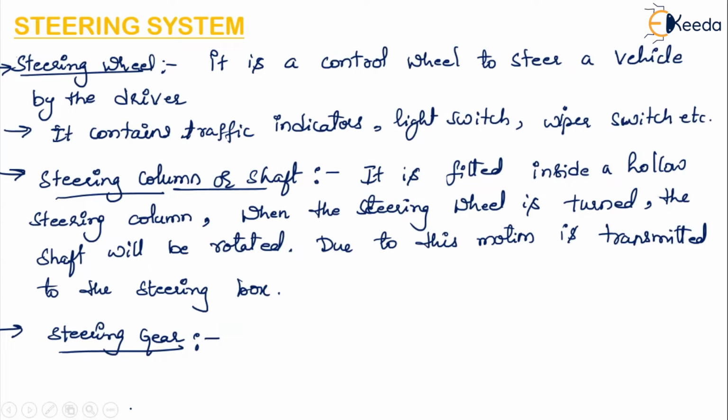The steering gearbox contains the gears that transmit the driver's steering input to the steering link that will turn the wheels, and it multiplies the driver's steering changes so that the front wheels move more than the steering wheel.